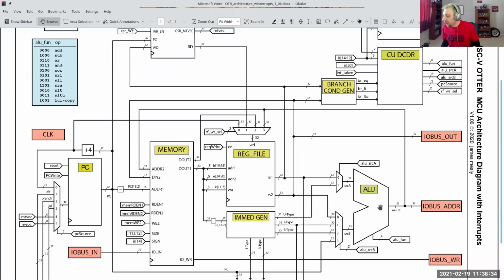I don't see any really poorly designed ALUs. But then the other thing that's sort of an unknown is this decoder, right? And so if this decoder is slow, then these ALU source selects change late, which then means everything that happens after them is happening later, right? And so that could be a problem.